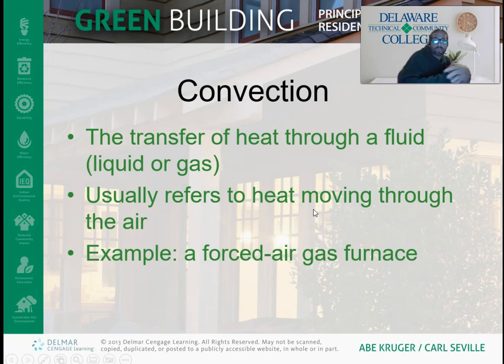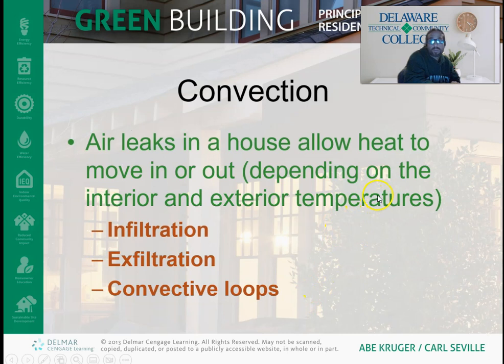So remember, heat transfer through a building envelope is mostly conduction, although there is some convection and radiation. Convection is when heat is traveling with a fluid. Most often we refer to convective currents in the air, but you can have it in water as well. That happens when you have a hot water heater, for example. You have these little convective currents inside. It's called a thermosiphon. But you can also have forced convection like you do in a forced air furnace. Like if you blow a fan, that's forced convection.